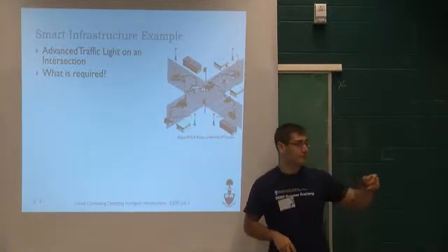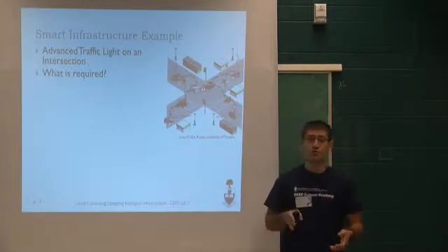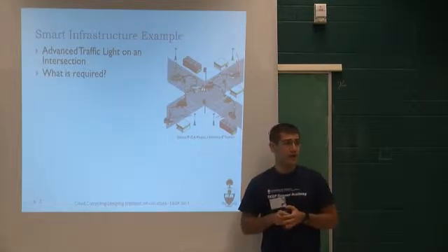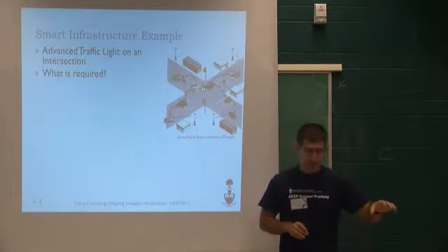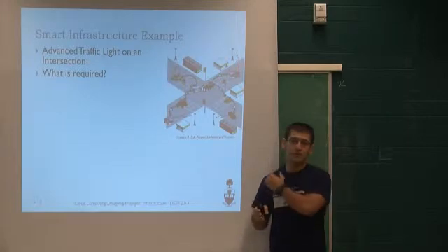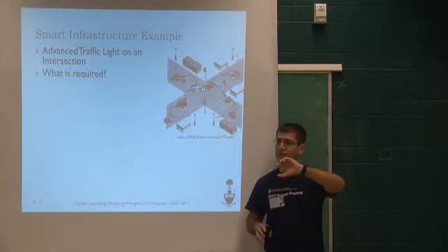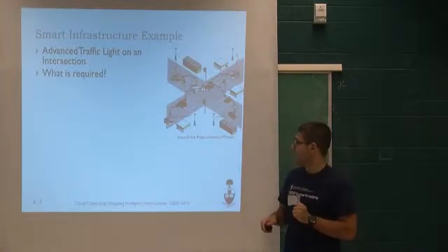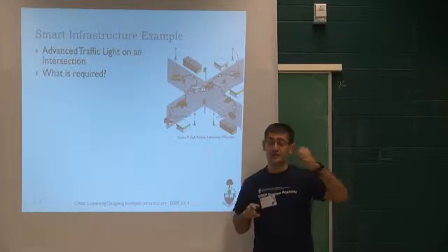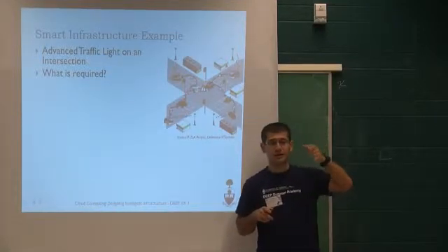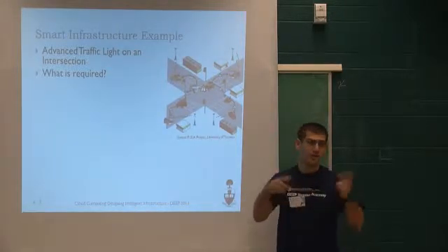And then in addition to that, at night, usually those pre-timed signals get changed into actuated and fully actuated, which means that they depend on additional sensors. So when you have no vehicles coming on a small approach, then the north-south one, for example, would always have a green light. Unless one vehicle comes, that gets detected, and then the traffic light switches after a few seconds. If you want to know about these further, we covered these in the course last year. It's day 5. If you go through the website, it's recorded there, and the students are actually presenting this material.